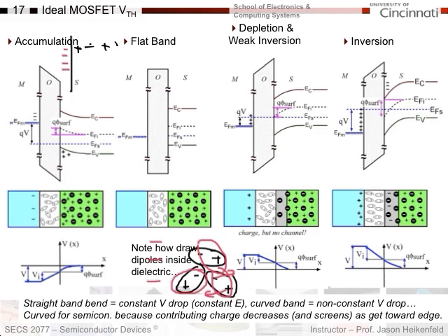It reorients a little bit, positive, negative, and the next one, positive, negative. So you can see how all these molecules can basically rotate as necessary, just a little bit. They don't actually rotate this much, to line up their positive ends with the negative charge. Its next molecule is positive with the negative next, and this kind of feeds through the oxide.